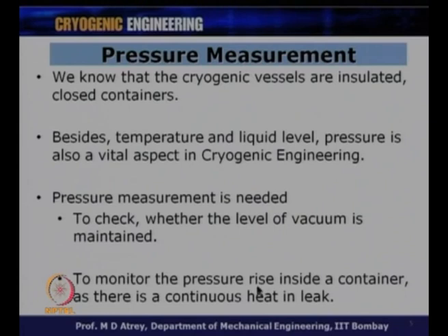So, if the boil off increases, if the heat inleaks increase, the pressure will rise in the container, and that also can be monitored if we find that this is the important parameter to be monitored. However, there is normally a safety valve which will open if the pressure exceeds a particular predetermined value. So, this can be normally taken care of, while the vacuum is the most important thing to be monitored.